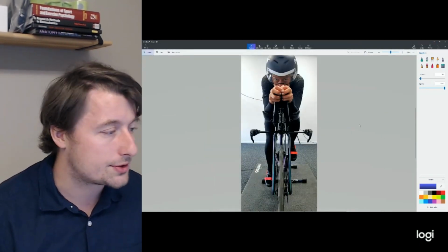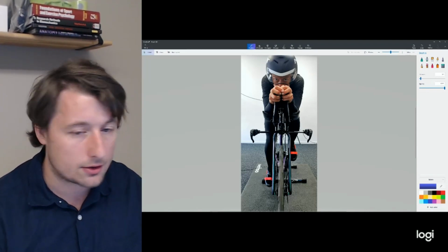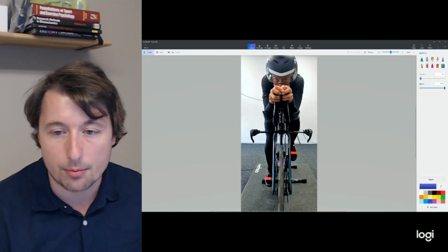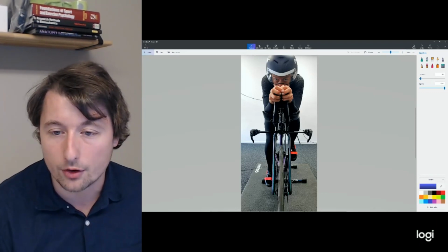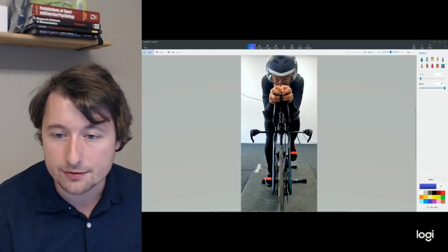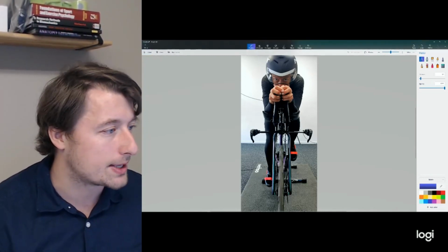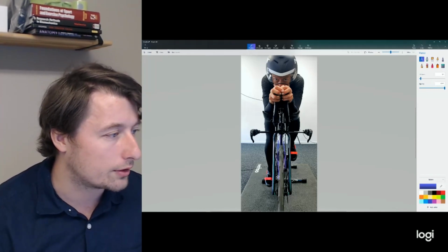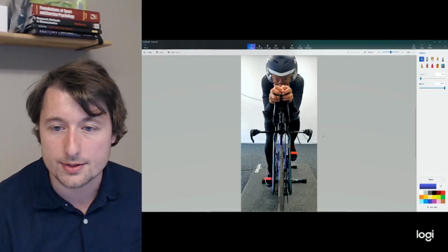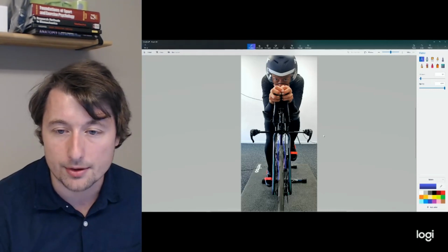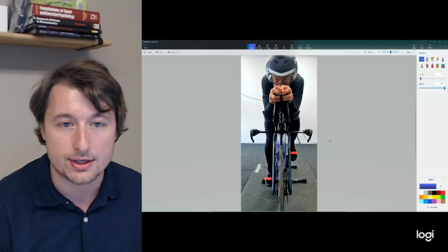How we can do that with some setups, as you'll potentially have seen with some of the newer bike designs, like this Q cycle. There are other brands trying to replicate to some extent what Q started with, this wider fork idea, which allows the air to flow through the legs. So we're thinking about where the airflow is going to go. On this bike, we see these nice open channels from the fork, through the stays, and out through the back of the position, which, if we think back to the previous image, is going to fill that space behind the cyclist as best as possible, reduce the wake and the turbulence, and allow you to move through the air better, which in turn is a better CD aspect of your CDA.